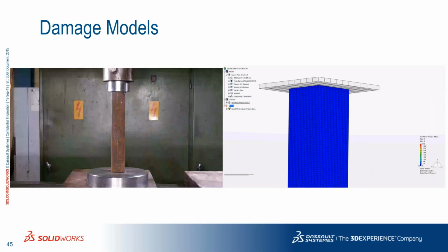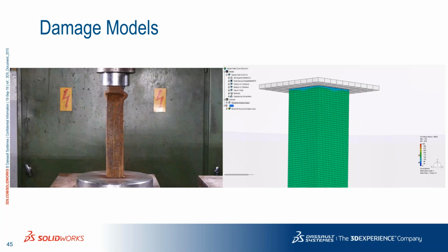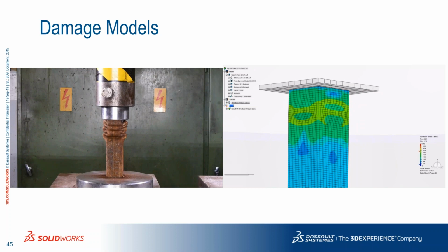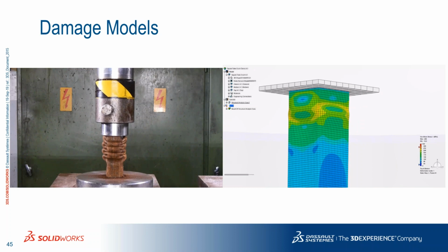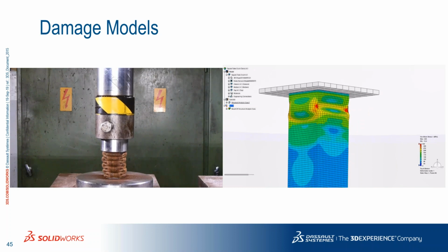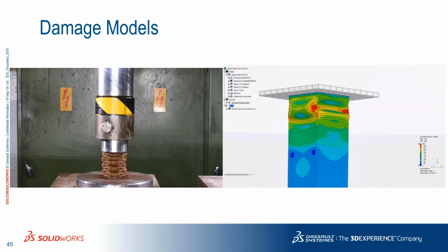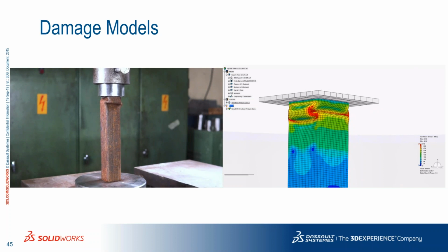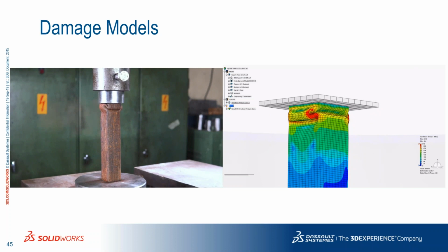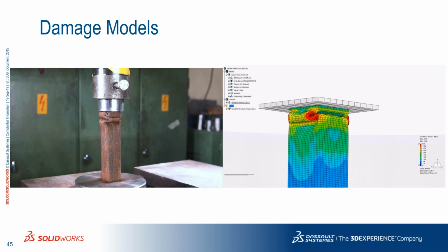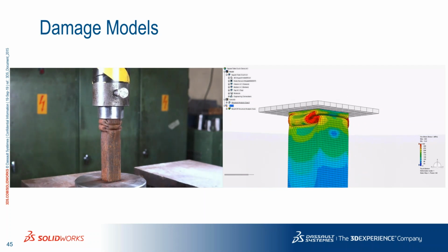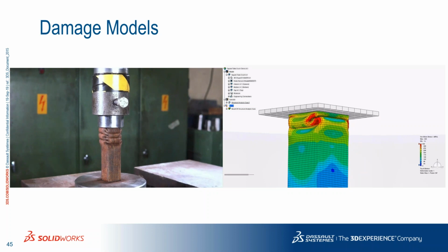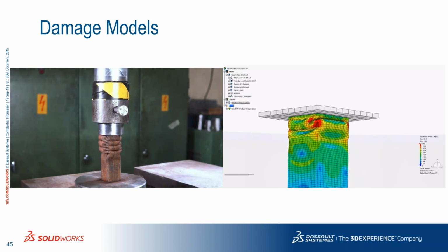So let's finish with this one. Also in this case I've applied the damage model, but in this case I've used the Johnson-Cook model. So here we are seeing a buckling, but a very complex buckling, because we are seeing the profile that is completely failing due to the compression load. And we can see the same results in the video. Very impressive to see in the simulation.